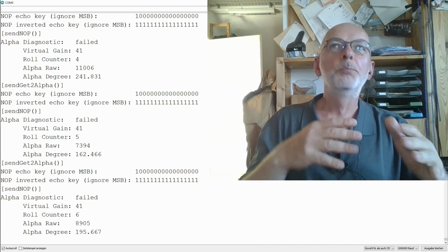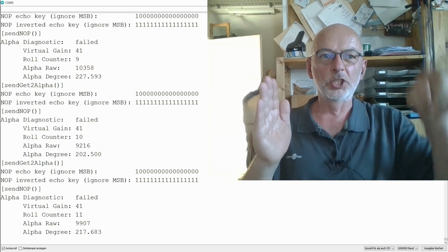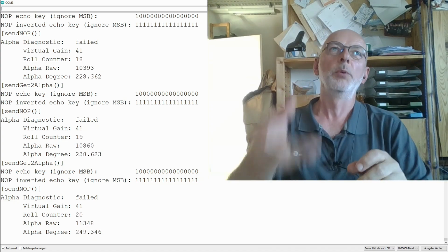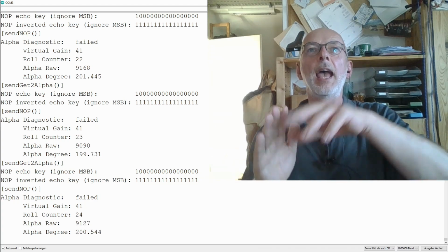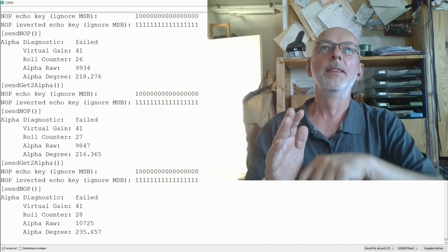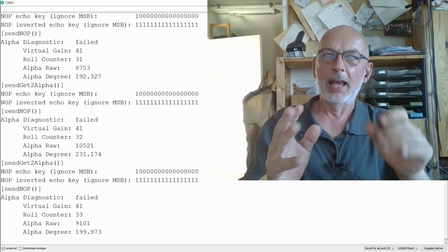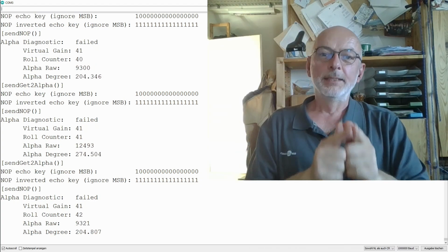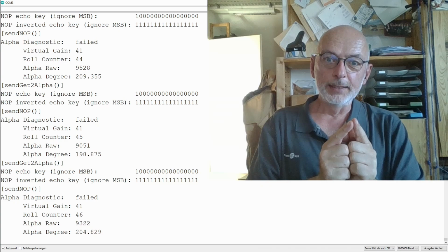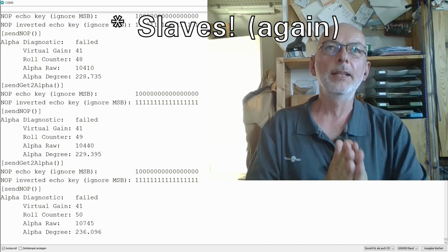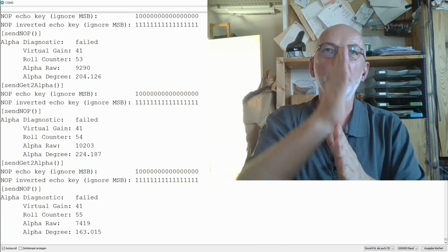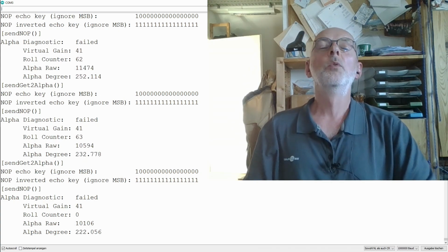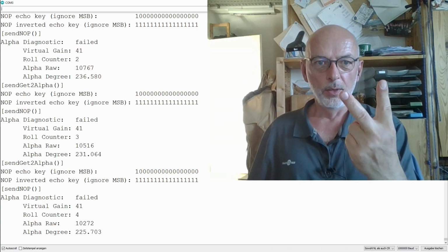However, you pay for that with an additional interleave of 2 SPI transactions. So you request some data and you get the data back after the next SPI transaction. And if you have several clients and you really need to take measurements with all the slaves at exactly the same time, you would go to trigger mode 2.